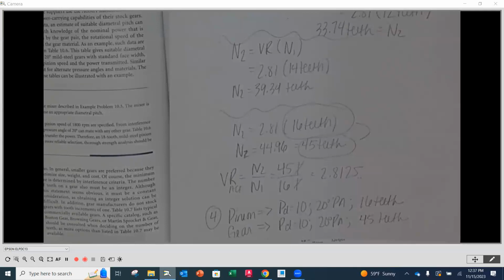Okay. But this would be what you would specify kinematics wise for a gear. This completes the kinematic problem for 2 gears that are in mesh. Then we would take it the next step further, machine elements. And now we would start looking at material and heat treating and all sorts of things. Looking at the stresses that are created. Okay. But kinematics, we don't worry about that just yet. We're just looking at motion that needs to be achieved.